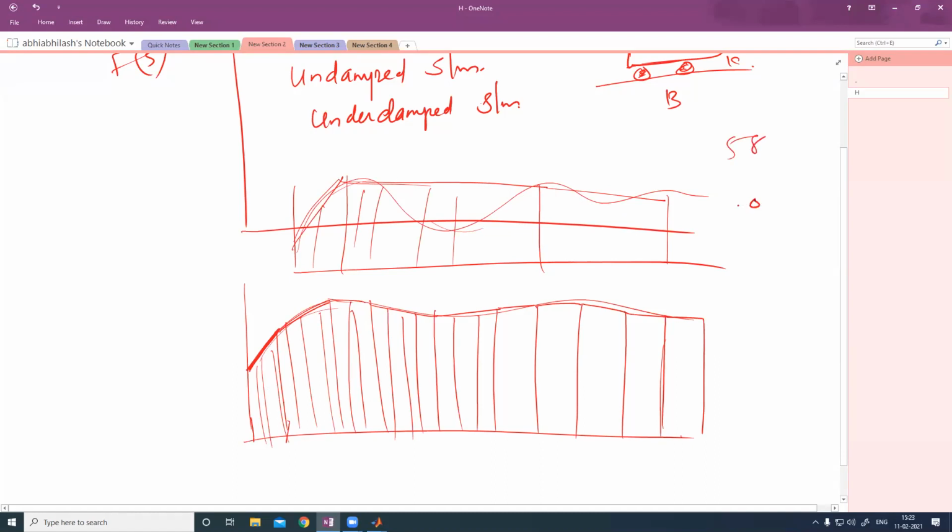Now if you are using 0.001 and 30 seconds, you will get this many sampled values, and the curve will look very good because the integration is taking more samples. MATLAB also works like that. MATLAB is actually a digital computer, so it is digitalizing the signal and using numerical integration techniques to solve these equations.